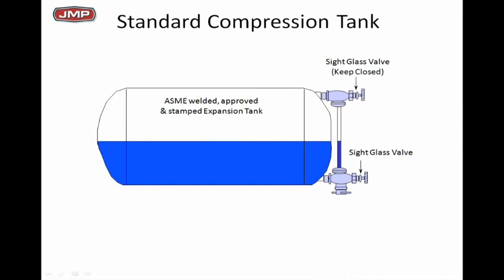Here's another picture of a standard expansion tank, steel tank, water in contact with the air. The way we did it for years and years and years worked quite well. In today's marketplace, I would suspect this is probably 10% of the market or less, and the diaphragm bladder type tanks are probably 90% plus of what we see. But you're going to see these, particularly on older jobs. You need at least to understand that they work and how they work.